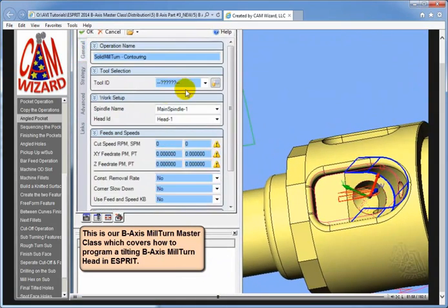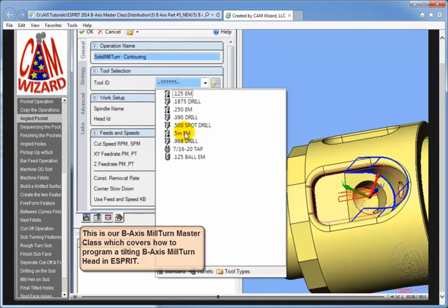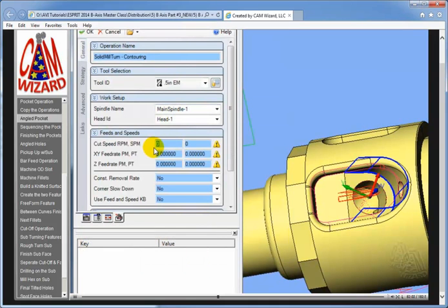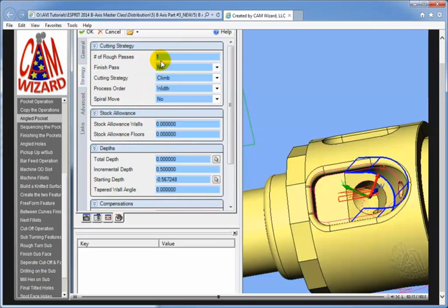Under the general page, under the tool ID, I'm going to select the same 1/2 inch end mill. I'll plug in the same kinds of feeds and speeds. I'll go 15, and this time in Z I'll go a little deeper faster because I'm clear of the part. I'm not trying to plunge here because I have this material already removed. Strategy, what am I going to do here? One pass, fine. Do I want a finish pass? Nope, don't need to.